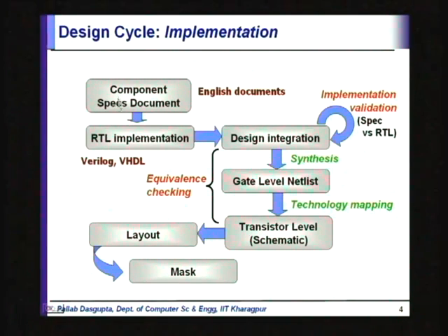Now, at this point the design entry is taking place. If you refer to the previous picture, we had a step called design entry. Design entry is typically done by first coding the unit level module. In the jargon followed in the industry, you have a full chip level, you have the block levels, and you have the unit level. The unit level is the smallest granularity module, or in other words, they are the modules which typically will not have any other modules instantiated within them.